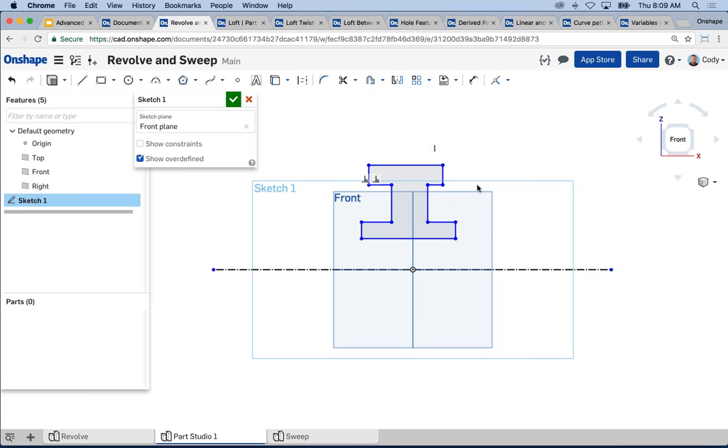So just a tip, you can mouse over anything as you're sketching, and it will wake up the reference for that. So now I've sketched this profile, and I want to center it over the origin. Now this isn't specific to revolve profiles, but just in my case, I want a clean sketch. So I'm going to construct a line from the origin, vertically, like so.